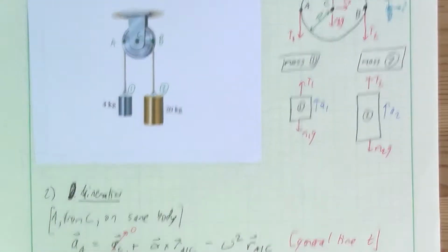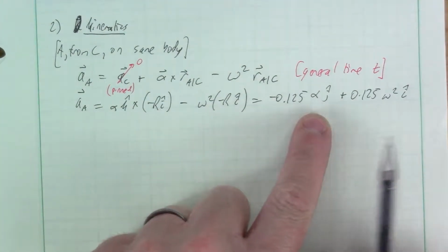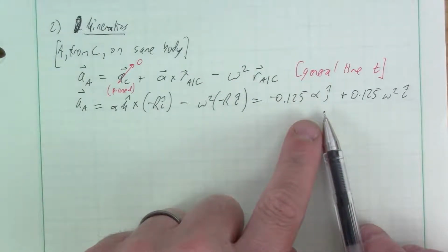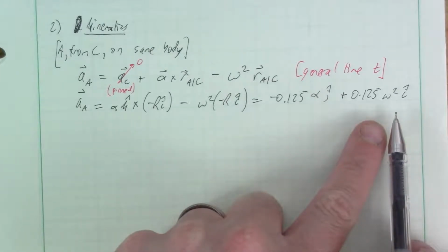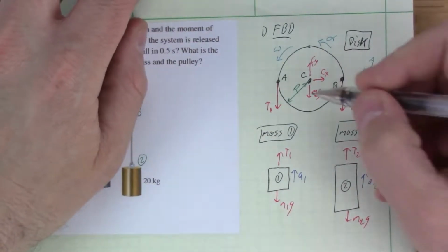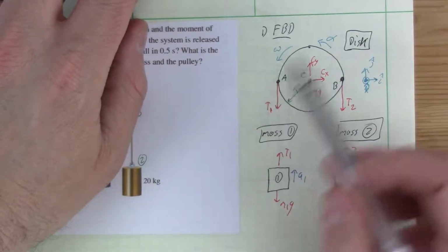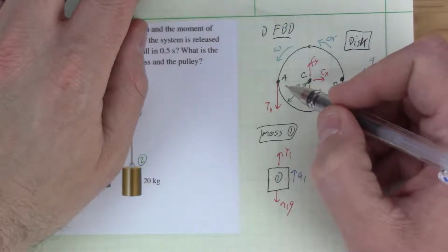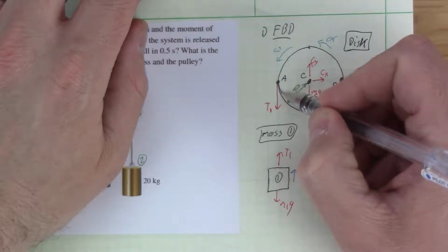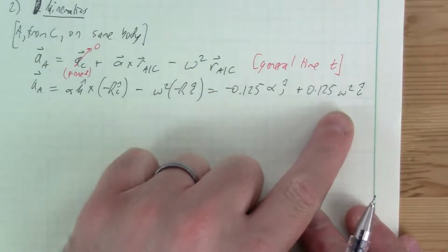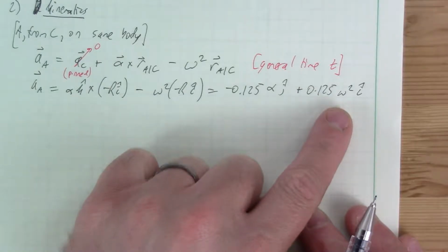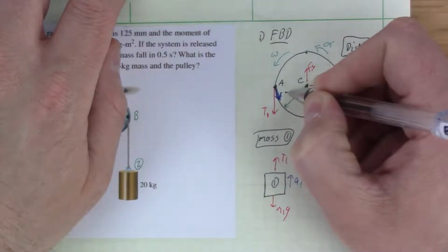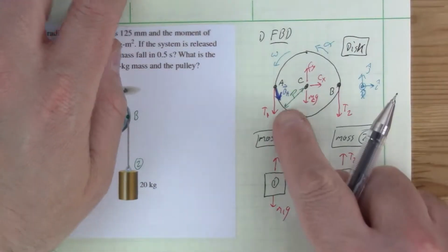What we want to do is relate, because you see now, what we got is that if alpha and omega are in the correct direction, that means that this accelerates downward in j, and rightward in i hat. Like we said, that kind of makes sense. If it was accelerating this way, we know it's the other way. These will both be negative, so everything's going to be flipped around here. But this actually accelerates downward and inward to the right. Oh, and I should say, even if omega is negative, that's always going to be to the right, because that's an omega squared. So maybe I don't know exactly how it's going to be pointing, but something like this. That's the absolute acceleration of A.